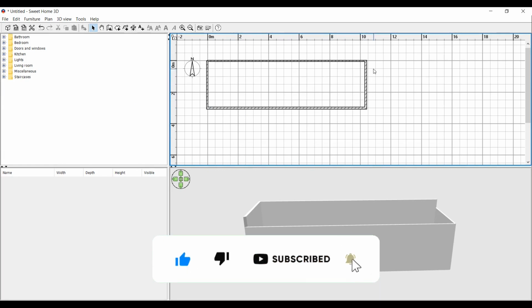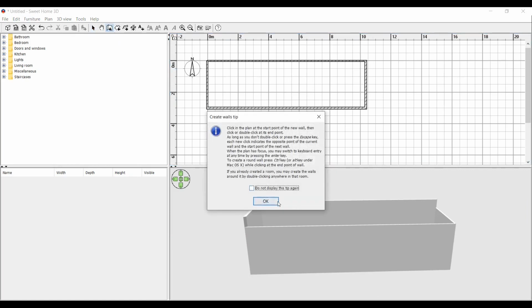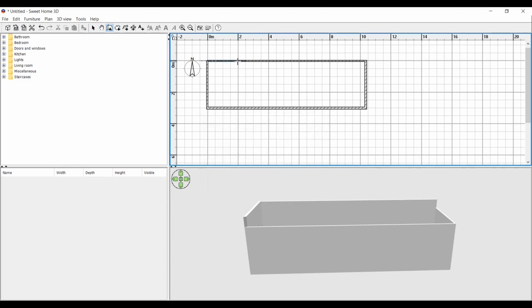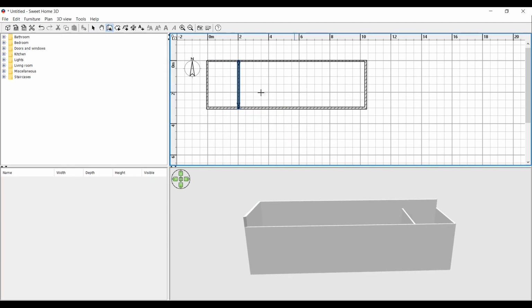Okay, I think there is nothing special left about the walls, although it's not complete yet. You see that now you can draw an interior wall using the same method. For example, here I create a bedroom. I know that it needs a door, which I will teach you in the next sessions. Okay, now we want to draw a floor.